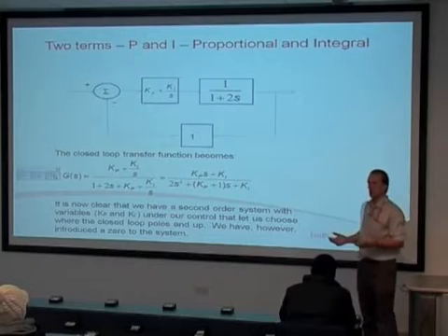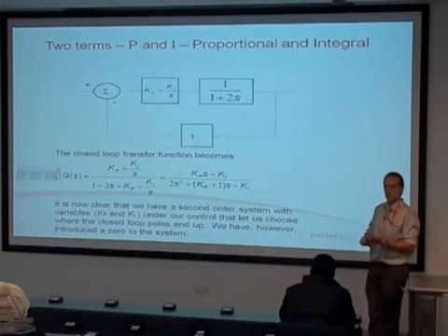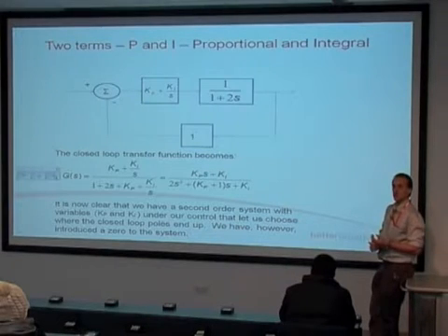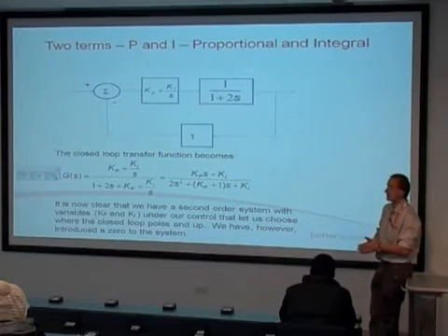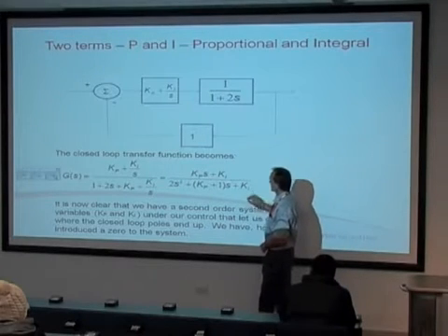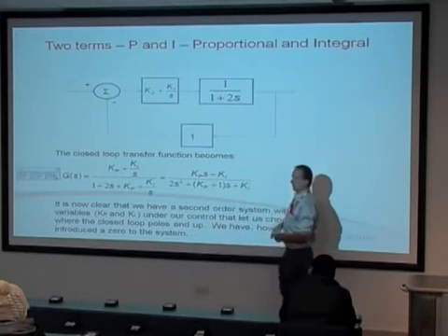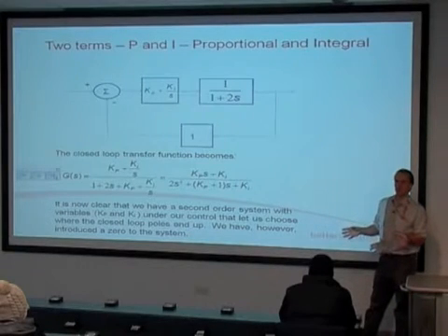That means I've got control over both variables in that quadratic, omega n and zeta. Which is kind of neat, really, because if you can control both of those, you can do what you like to some extent. So by configuring my controller this way, I've got full control over the resultant dynamics.